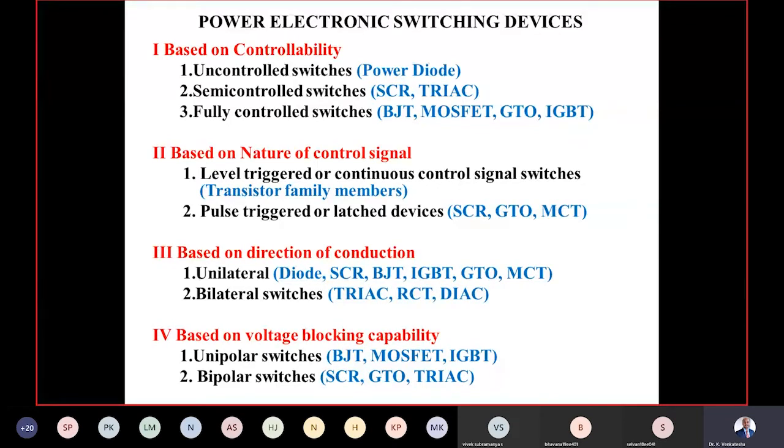So is it capable of handling that? Is the question. Yes. BJT, MOSFET, IGBT, all your transistor family members can handle this high voltage in one particular direction. Maybe collector positive, your emitter negative. It can handle one particular direction. But you give the reverse voltage, it will burn.